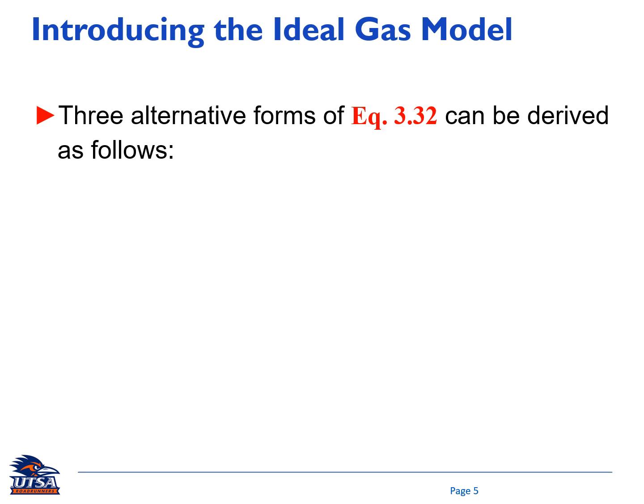So go back again to equation 3.32. I write it down again here that we have P times specific volume equal to R times T. R here is the gas constant, it's not universal. The one that's called universal is when we have R with an over bar. So here is the gas constant, R. PV equal to RT is for ideal gas, where Z equals 1.